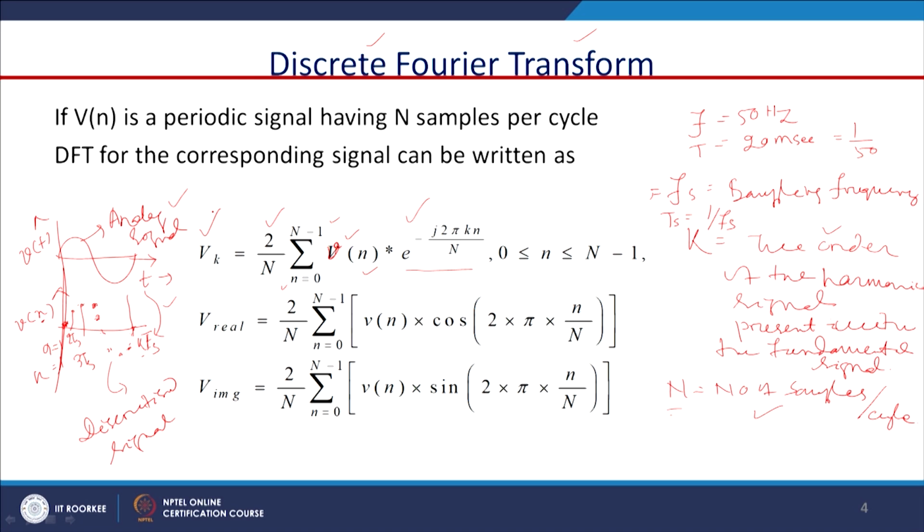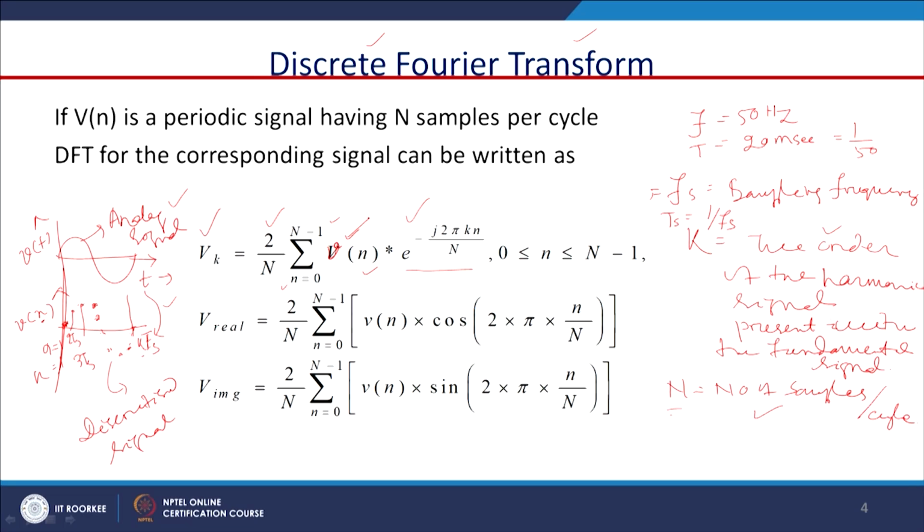Phasors mean the frequency domain is a must. We should know at what frequency we are going to calculate the RMS value of the signal and the phase angle of the signal. So that is why this is our discretized time domain signal, and we are converting it to this frequency domain signal for calculating the magnitude and phase angle.